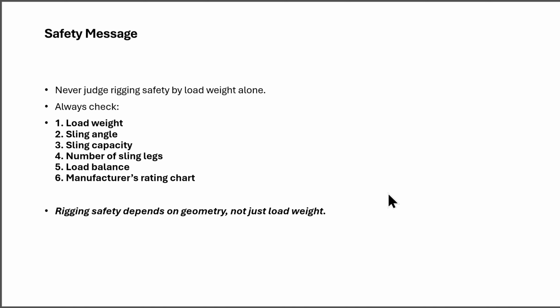I need to mention that before lifting, workers must check the sling angles and compare the expected sling tension with the working load limit. A sling may look strong enough based on the load weight alone, but the actual tension may be much higher because of poor rigging geometry.